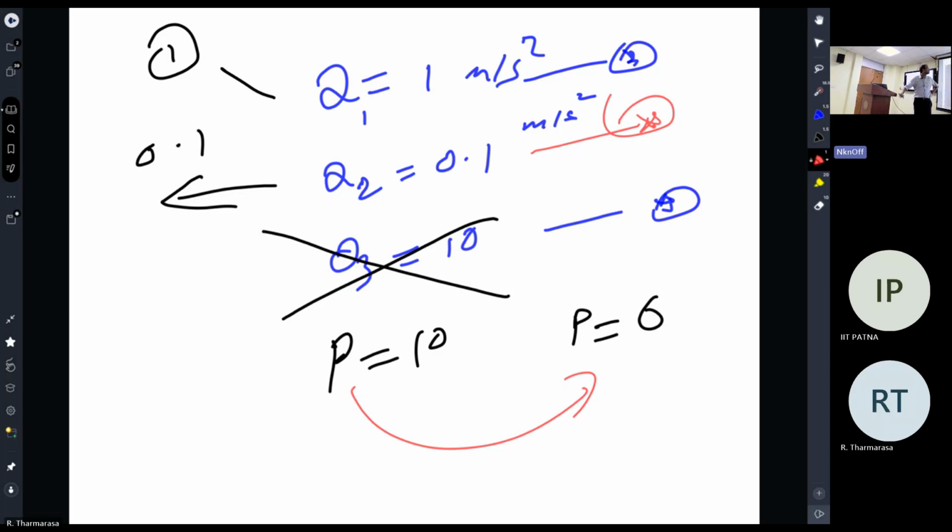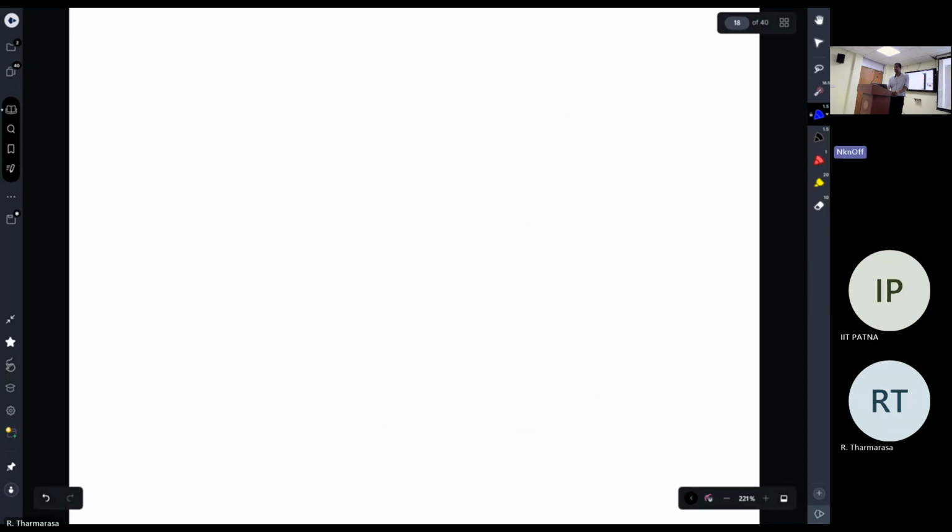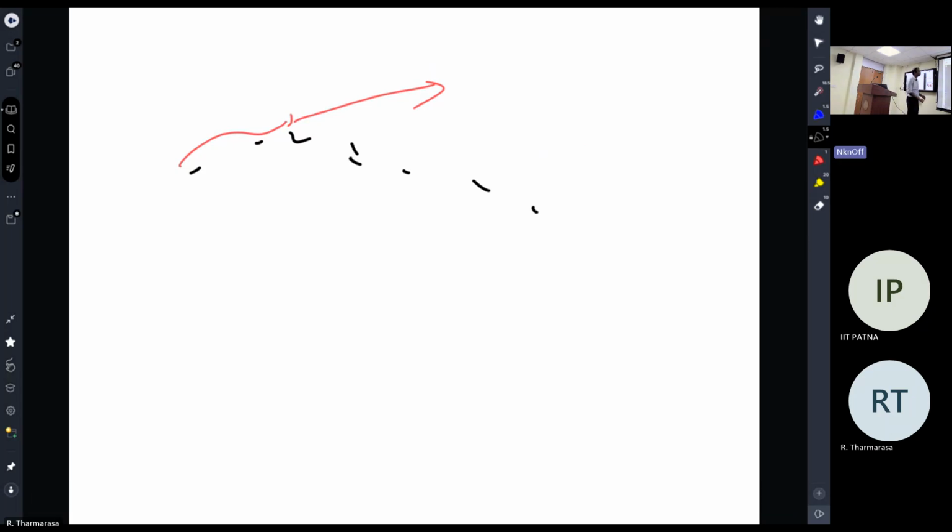When we do tracking, if the target goes like that and you use a lower noise, then this is what will happen. If the track is like this, and the target might go like that, but the measurements go this way. This is called track loss. The track comes here, and the measurement goes somewhere else, then your prediction goes somewhere.